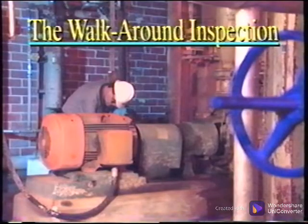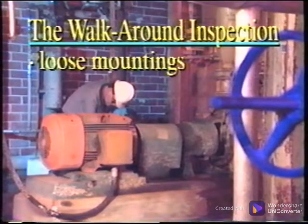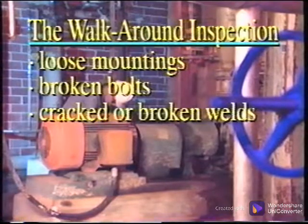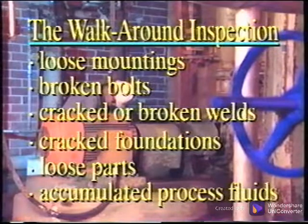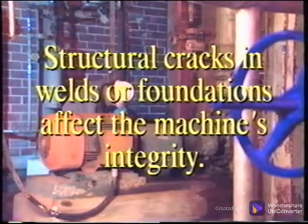During the walk-around inspection, check for loose mountings, broken bolts, cracked or broken welds, cracked foundations, loose parts, accumulated process fluids or solids. Structural cracks in welds or foundations may seriously affect the machine's integrity, causing unstable phases and changing the resonant conditions of the machine. Don't underestimate the value of this walk-around inspection. Many serious problems have been found and many unnecessary balance jobs avoided due to a thorough inspection.